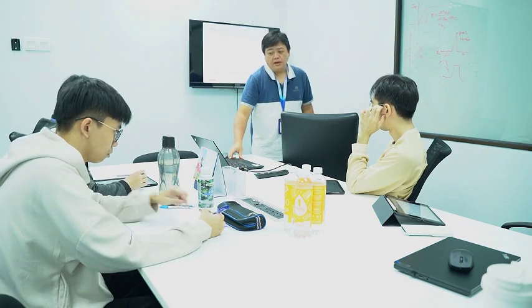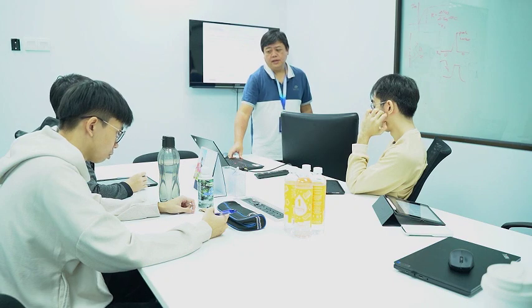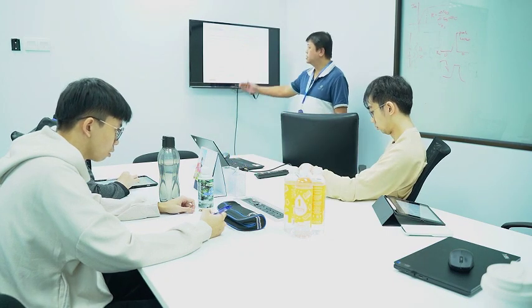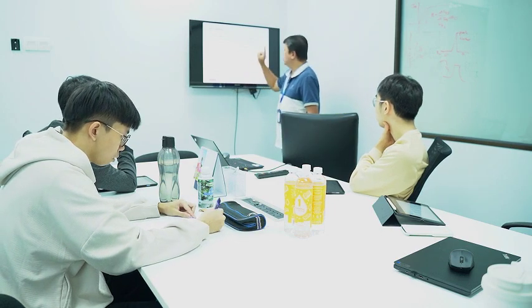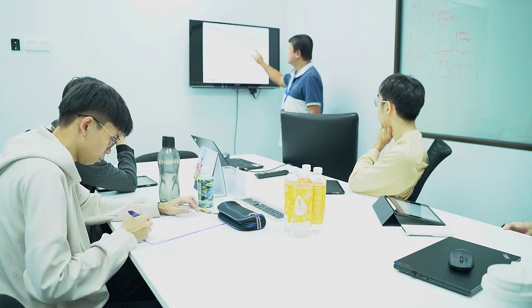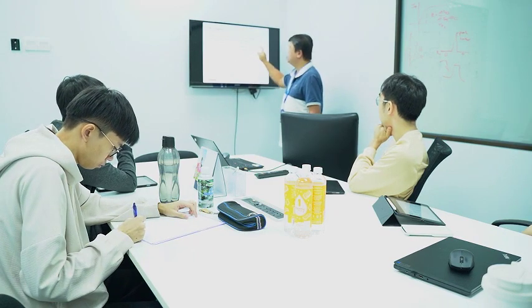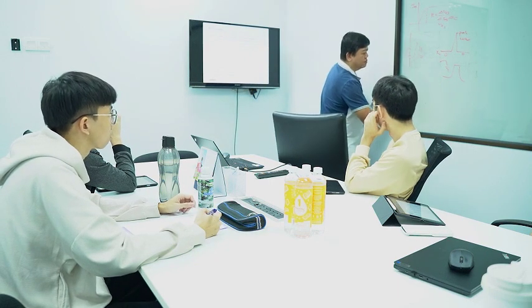And as I mentioned, the RC constant, right? The RC constant is very critical, especially if you are a designer, especially if you do the post-layout simulations, right? Your R and C will affect your rise time, fall time, and also the propagation delay, right? So how to control it? That's why I told you there's an RC constant: when you reach 1 RC, your output will be equivalent to 63.2%. Let's say you have 1 volt input. I think we did a simulation yesterday. You do a simulation, then you have an RC.